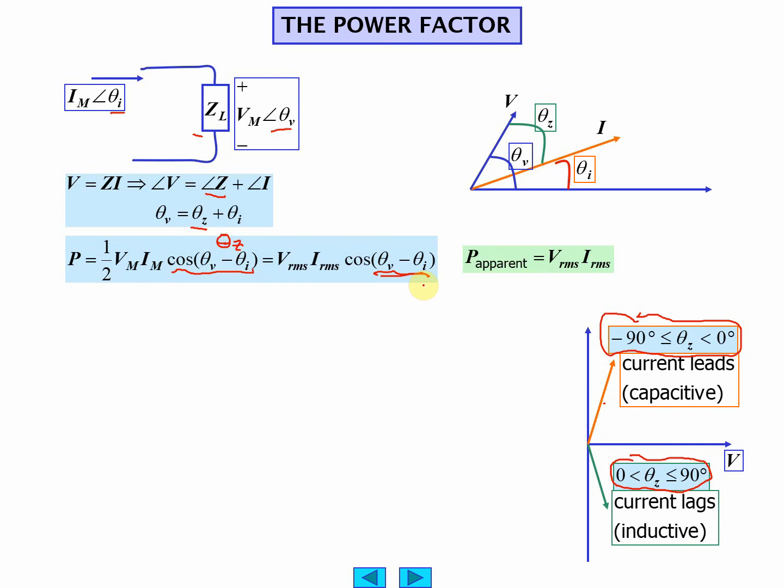So we can use RMS here instead of this. You can use RMS. So now it's starting to look a lot like the DC case. You don't have to worry about these 1/2 values. This is actually more accurate. We saw a square wave, a triangular wave, different waveforms. If you're getting true RMS, then this will be the true power. This is only true for sinusoidal.